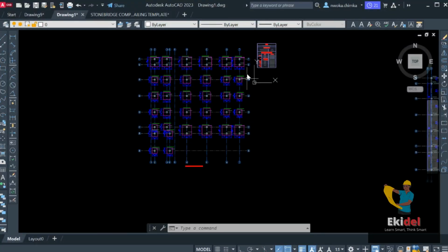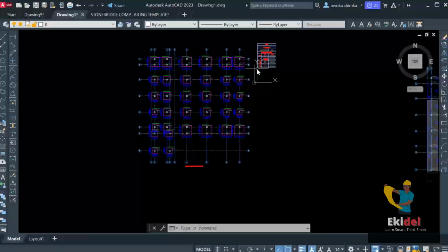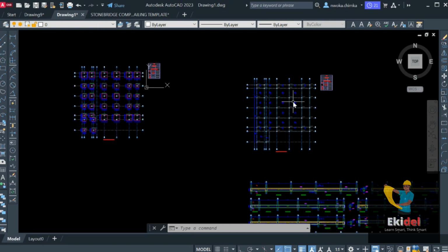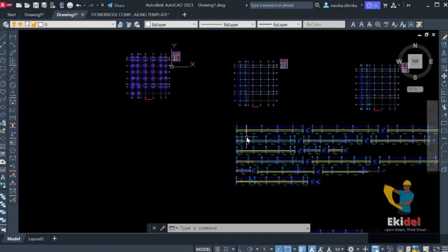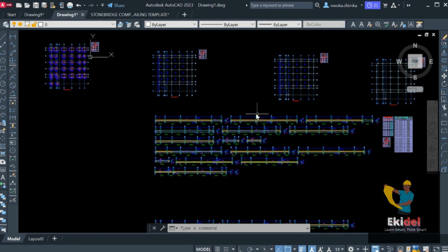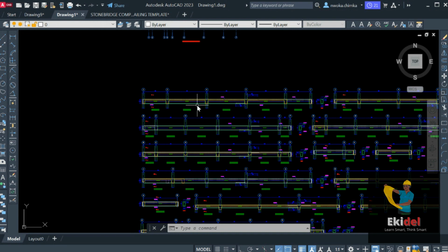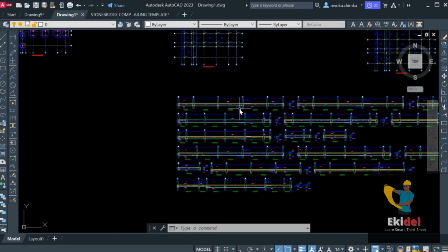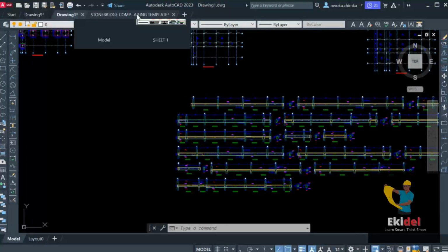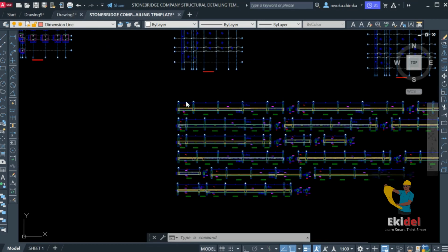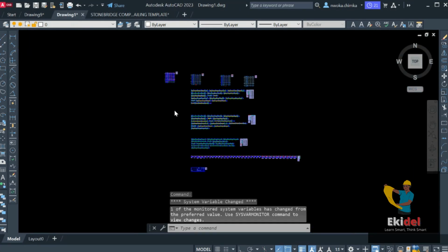Now, if you print this directly without any editing or without these templates, your printout will not be visible because this exported file from Prota Structure was not set. The software only did its detailing for you. So right now, we will go back to the templates.